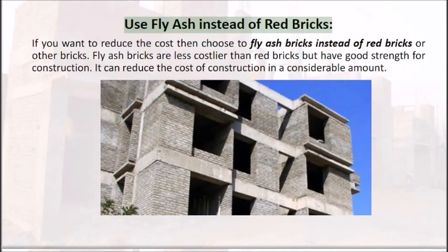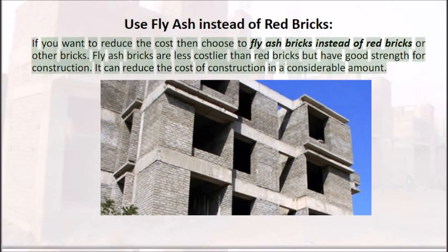Use fly ash instead of red bricks. If you want to reduce the cost, then choose fly ash bricks instead of red bricks or other bricks. Fly ash bricks are less costly than red bricks but have good strength for construction. It can reduce the cost of construction by a considerable amount.